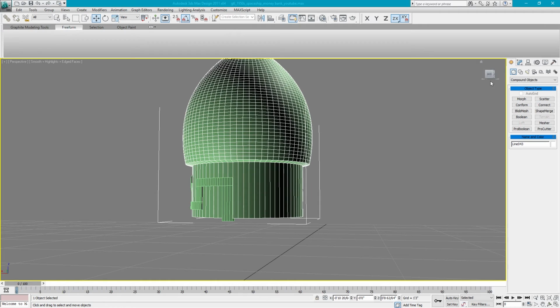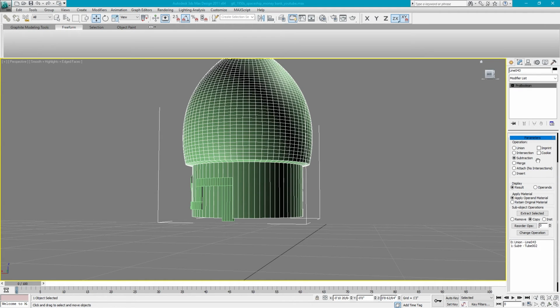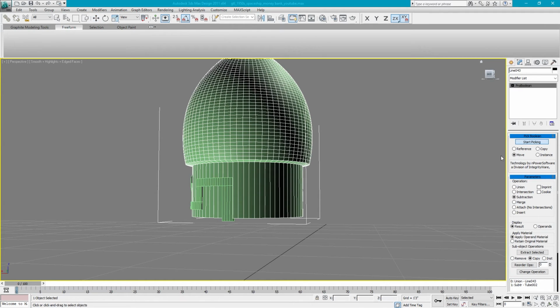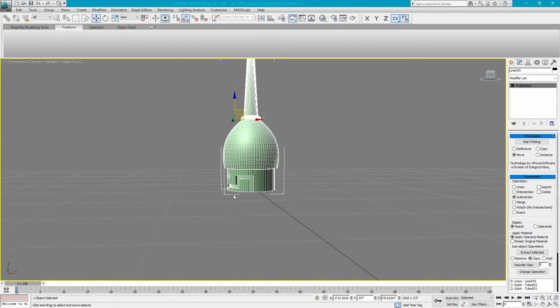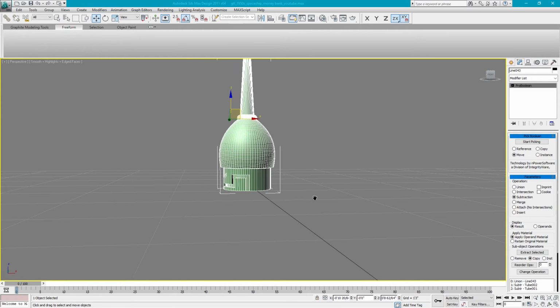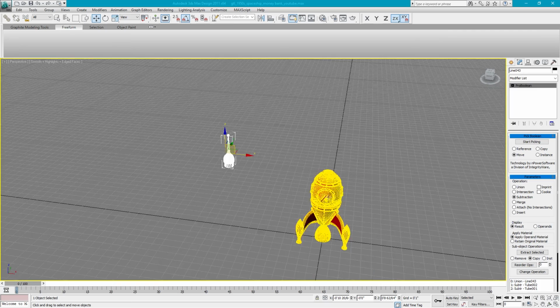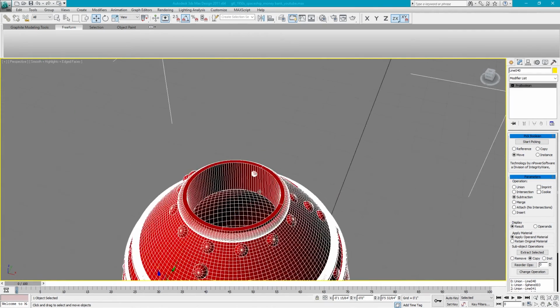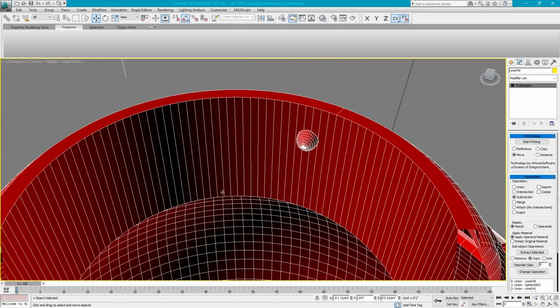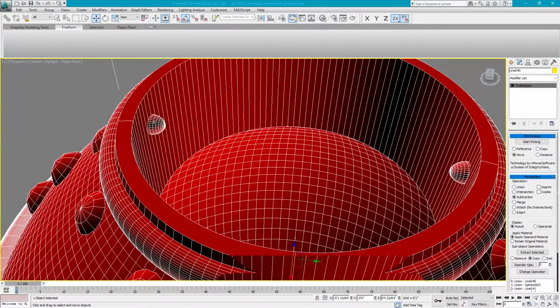And then also I can go ahead and go to subtraction. I can add more than one thing, so I can just pick another one, subtract it out, and there you go. So the cool thing with this top little locking mechanism is you can make 10, 20 different designs of different shapes or whatever, so that no one knows how to get in your little money case here. And here's the little spheres that actually lock into the keying mechanism.